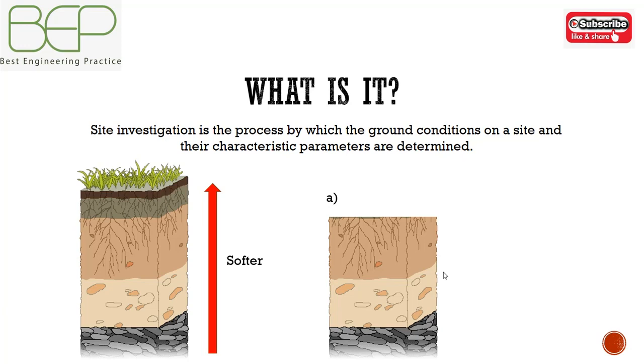In the first case, the structure might have to sustain lateral earth pressures close to those in situ existing before construction, or more likely, if the wall was allowed to yield away from the soil sufficiently, active earth pressure, which would be determined from in situ soil properties.